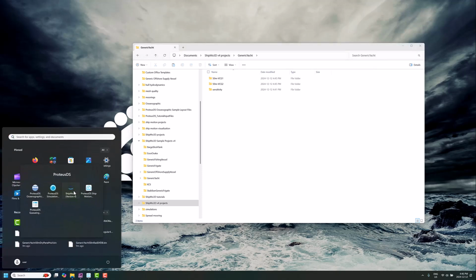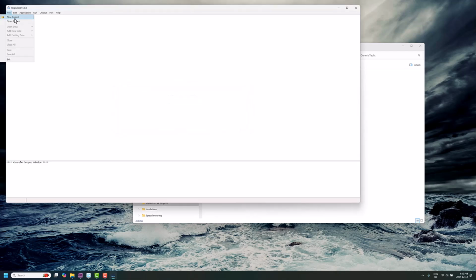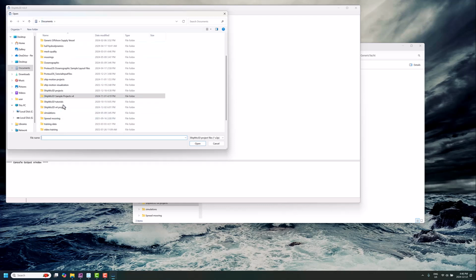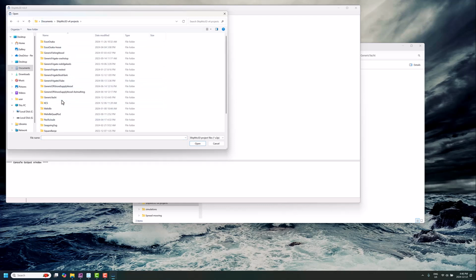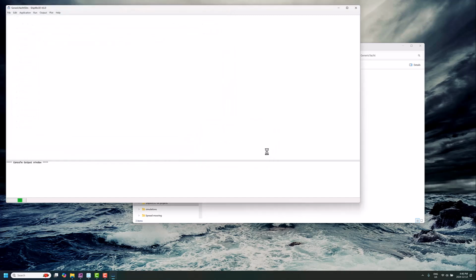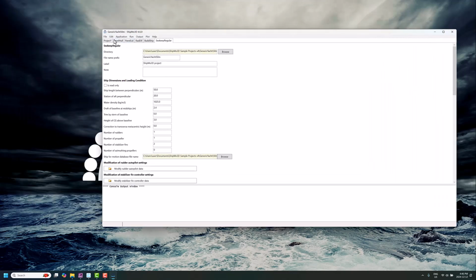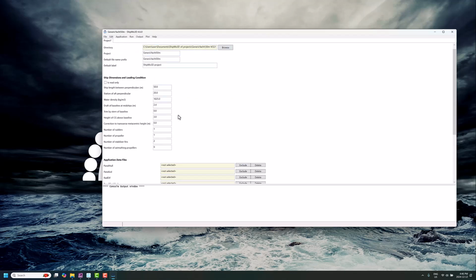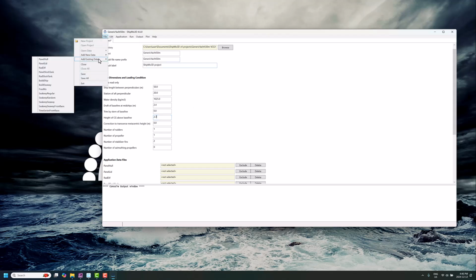So first, we'll open up the first project. I do also suggest you go through it one at a time because the software is going to remember the last folder that you opened up, and it can get really confusing if you start trying to do things one at a time. So I'm just going to exclude all of this stuff, so we're starting from a blank slate. This is VCG1. We're going to change this to 2.7, so that's 10% lower than the nominal value for that 50-meter generic yacht. And we'll go to add existing data.